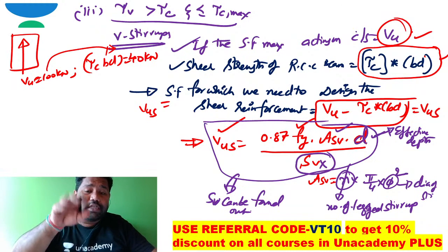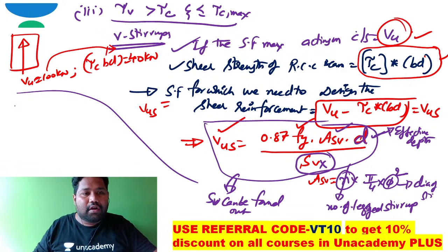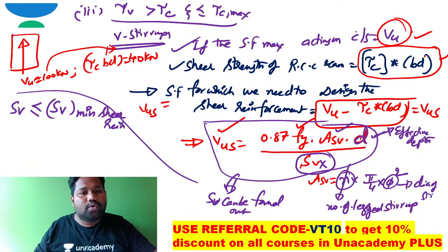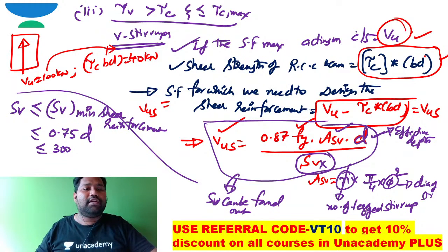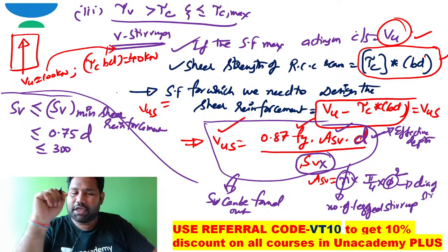But will you provide this spacing directly? No, no, no. I just want to convey one thing. The Sv I work out should always be less than or equal to the spacing of minimum shear reinforcement. I already taught you how to find the spacing of minimum shear reinforcement. For vertical stirrups, Sv should always be less than 0.75 times d, and less than 300. This is how I need to design the spacing of shear reinforcement.